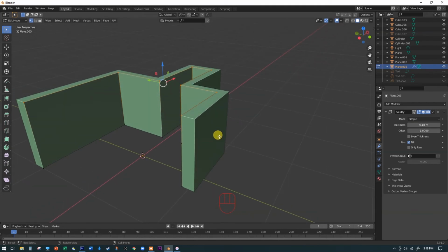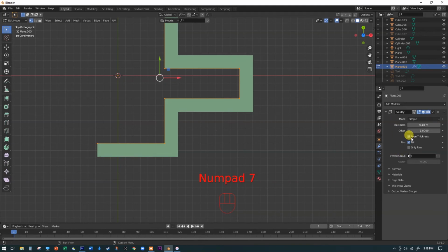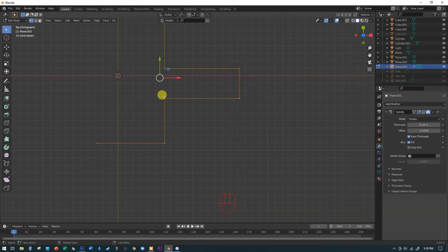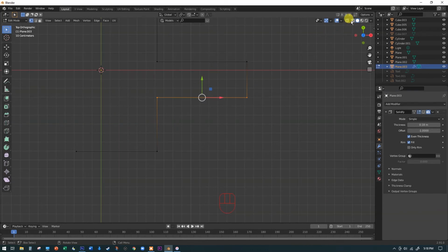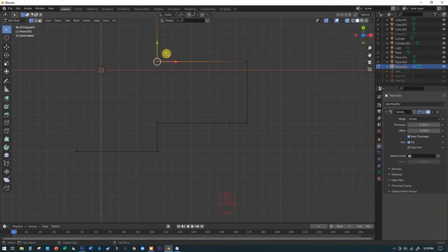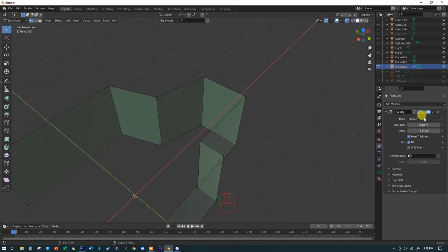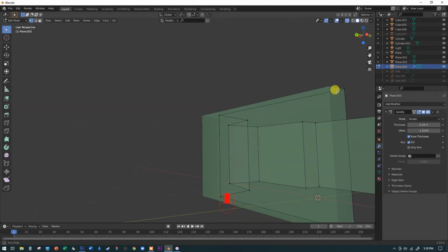And the nice thing about this again is that those walls are just one line thick. So if I want to go back in here, I can check on even thickness there, and I can even turn this off to make it really easy to see. I'm going to make sure I'm in X-ray view so I can grab all four, because this isn't just dots on the floor here, this is a wall now, and I can very easily move these around. Maybe I can make this wall angled. You can do all that sort of thing. And then you can come back in here and just turn your solidify modifier back on, and there you go.